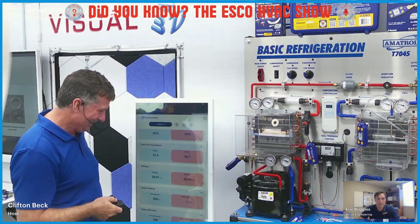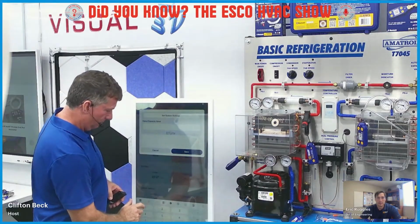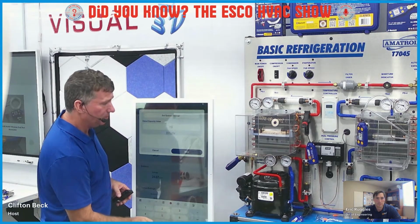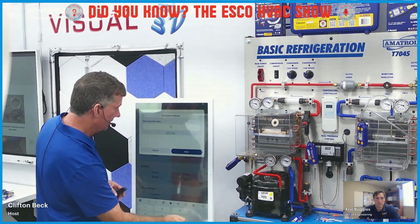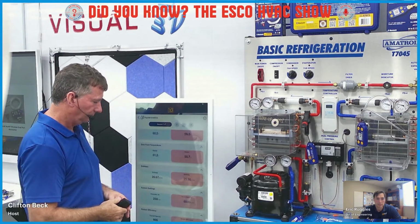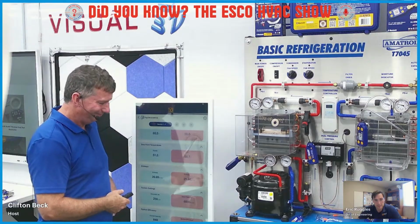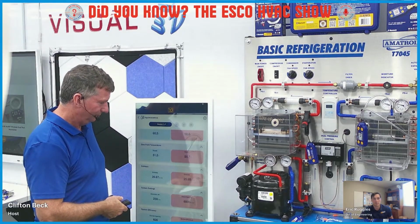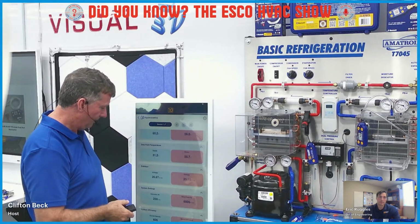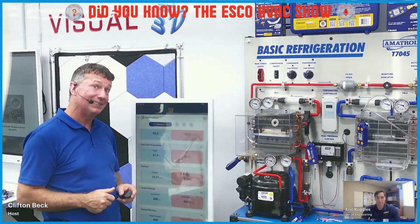That's fair. And then you would add this capacity as well, the red box on the right, a rated capacity of the system. I'm just guessing on this one. I don't know what the BTU of that one actually is, but we're going to guess that it's around, let's just say, 6,000-ish. Okay. Right. And then it'll use the difference in enthalpy and the airflow to calculate the actual capacity of the system, and then give you a system efficiency number based on what it's actually running to the rated calculation. Oh, okay. All right. Getting closer. Getting excited now. Okay, what's next?